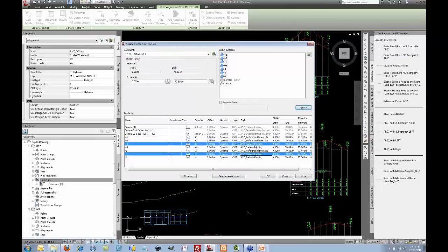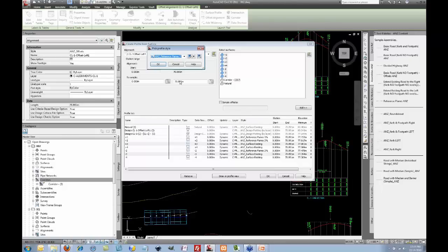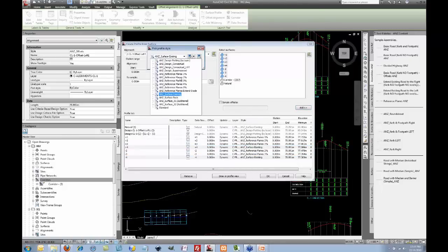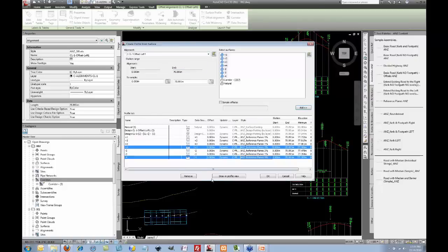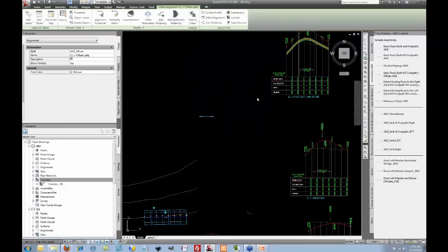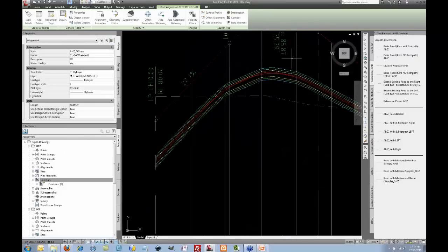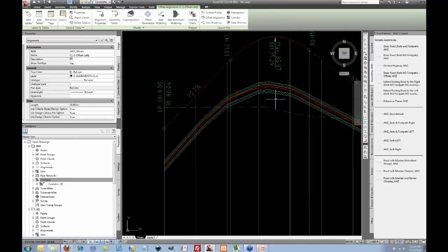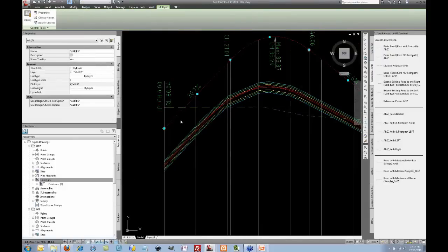Now somebody made a very good comment about this last week, which was about how the layers work. So let me just finish this very quickly. So I've now picked correct styles from my 1 to 4%, and all I do is press OK. A previous kind of misconception was that you had to redraw the profile view by pressing the Draw button. Once you press OK, that information gets added to the profiles, so you can now see on this view here the different colors corresponding to 1 to 4%. So you would then take your profile view and make sure that you fit within that range.